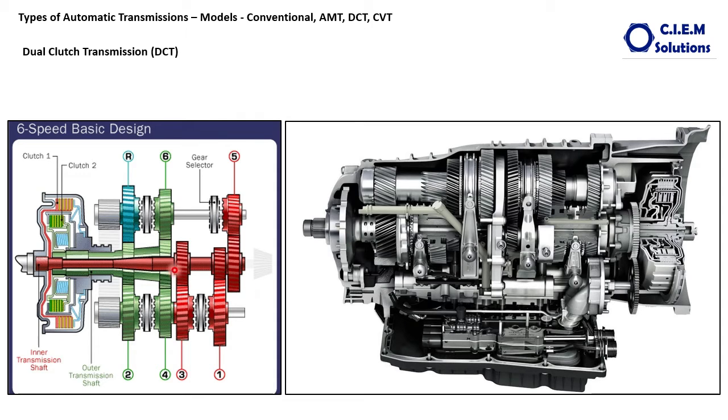Here also there is no need to press the clutches and no need to shift the gears manually. How does it operate? If you want to move the vehicle from the rest position, this clutch is pressed through the mechatronic mechanism and the first gear is engaged through this synchronizing unit. The lever movement takes place through the electromechanical system.